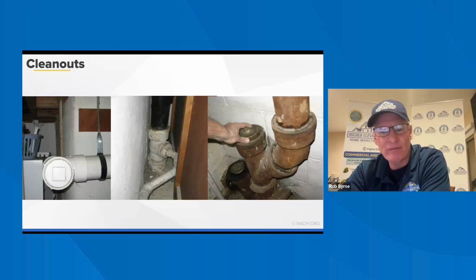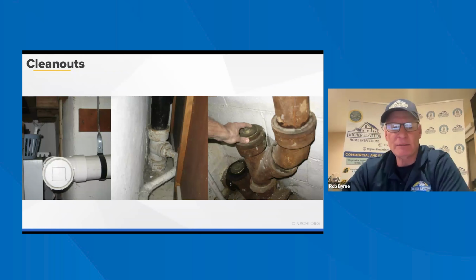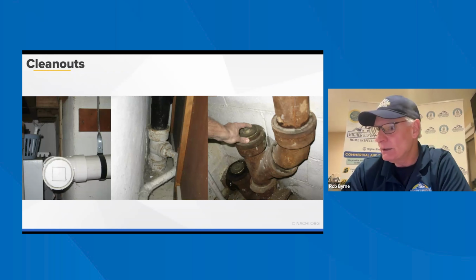Cleanouts, we talked about that before. There were a couple of slides before that showed the cleanouts. That's a cleanout where you can open it up and then clean out any blockage, or if you want to run a camera scope down there, you can. It's helpful for your clients to know if the drain's backed up. That's all good stuff, especially on older houses.